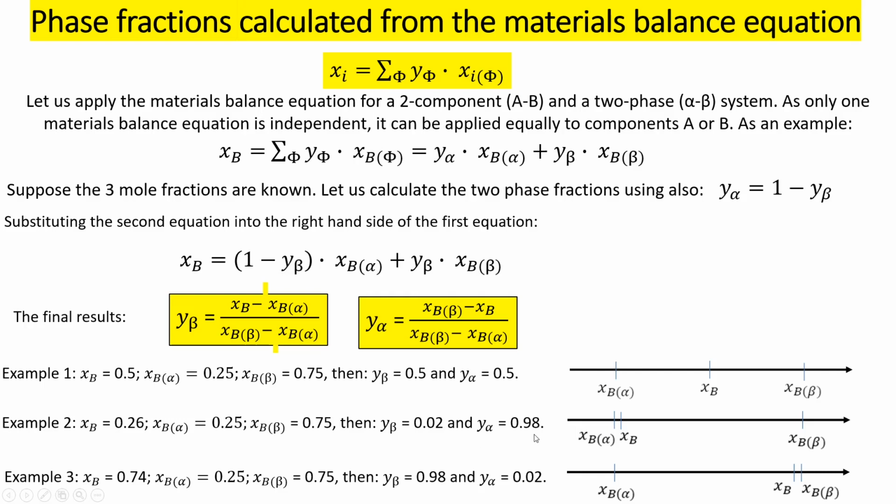Okay, for example, if I see this picture, and by the way, similar pictures we will see later in two-component phase diagrams. On X we will have actual XB, on Y-axis we will have temperature, we will have different lines, I mean solidus, liquidus, etc., which will intersect at given temperature, these XB alpha and XB beta values, and then XB actually will be given by us engineers, because XB is the state parameter here, initial parameter.